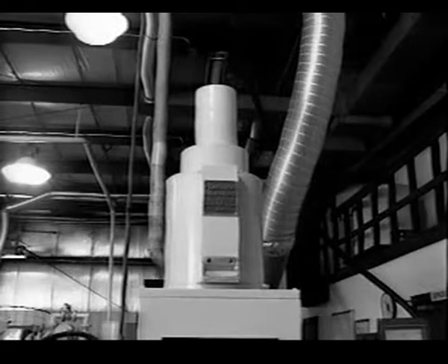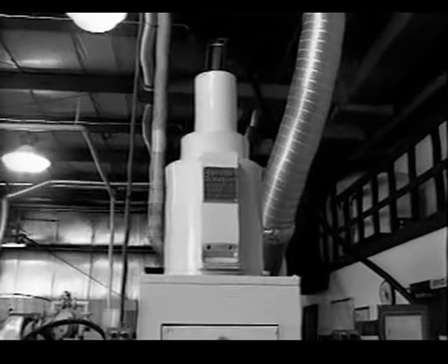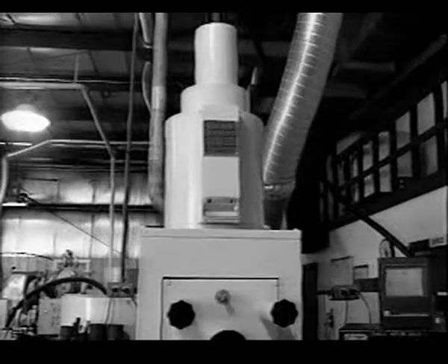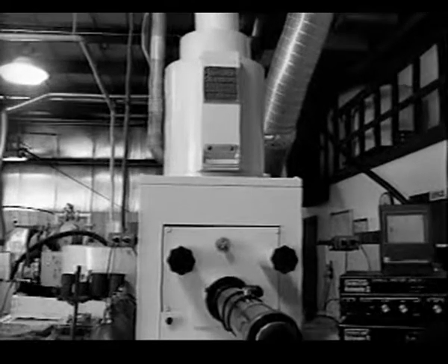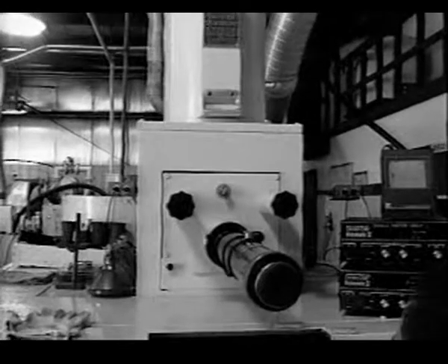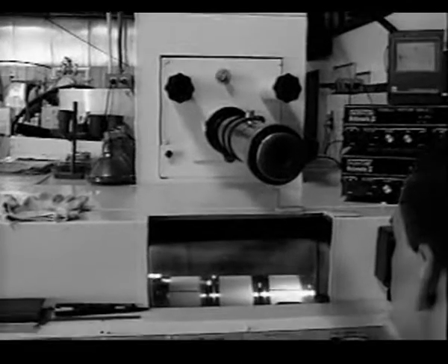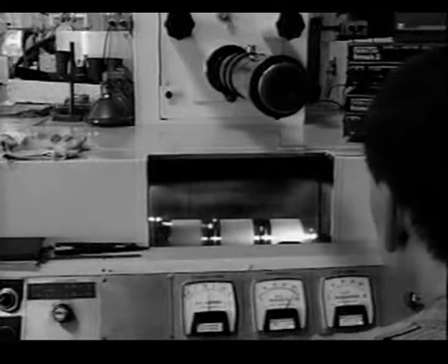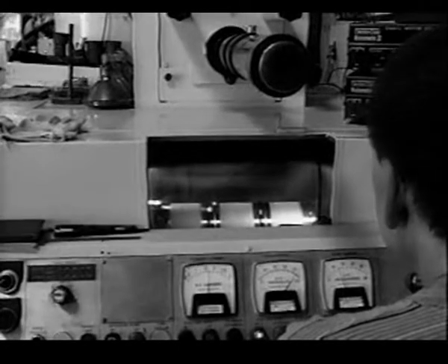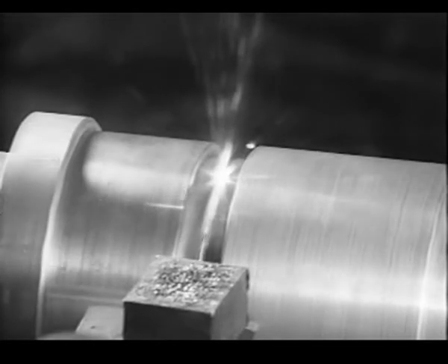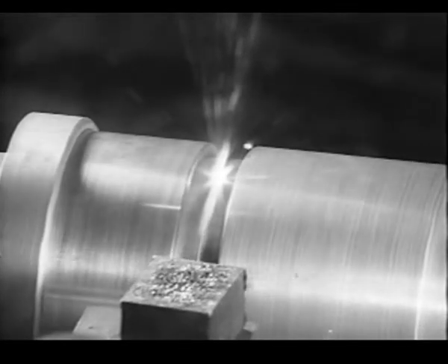In electron beam welding, the coalescence heat is generated by the kinetic energy of a focused stream of electrons directed upon the joint. The electrons are produced by an electron gun, accelerated to high velocity, shaped into a beam by electrical fields, and then further collimated or made parallel and focused by an electromagnetic lens. This electron stream is developed in high vacuum, but actual welding can be performed in either high vacuum, partial vacuum,